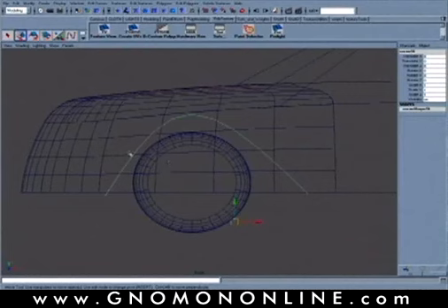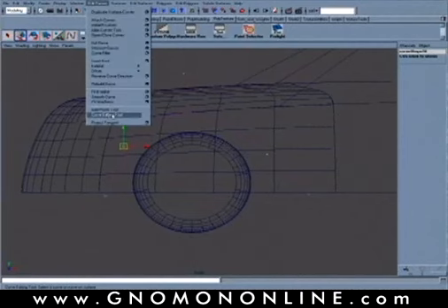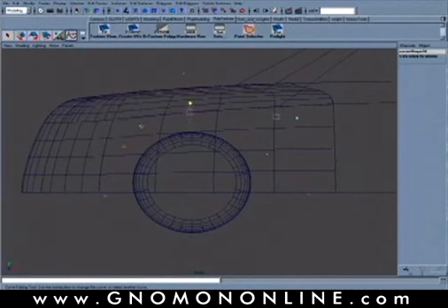Okay, to edit this, again, we can go in and grab CVs, be able to manually position where we want these, or you can use under Edit Curves the curve editing tool, which will give you this slider kind of parameter control to run along the surface and create our actual edit here.